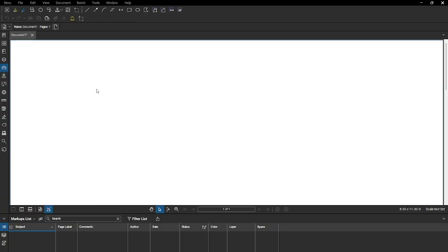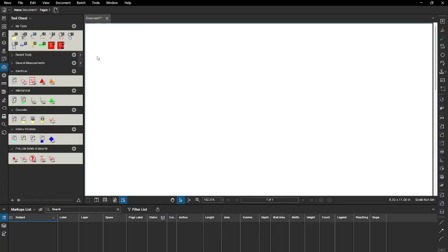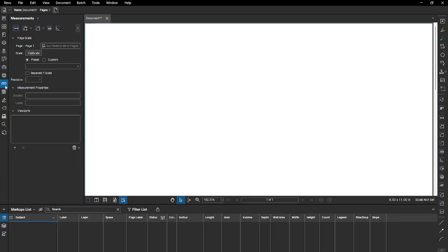Columns include custom columns and custom statuses, which can be extremely useful when it comes to estimating. Revu comes with a built-in quantity takeoff profile that you can start with. To switch to the quantity takeoff profile, go to the Revu profiles and select it from the menu that appears. If you were working in a different profile, you would notice that the interface setup changed when you switched.